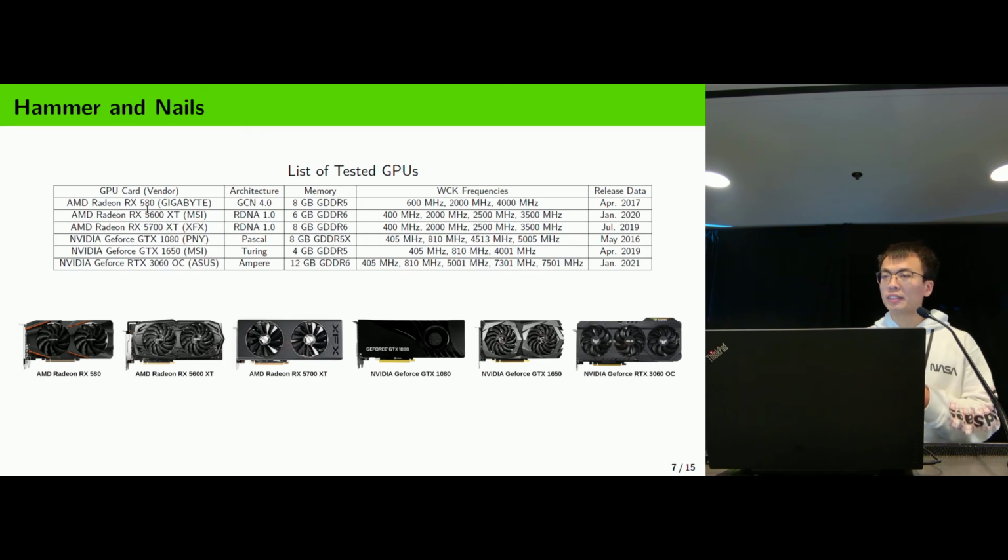This DVFS technique is independently implemented for the discrete GPUs, and for those integrated GPUs, the voltage is regulated by the CPU VRMs, so that's not in the scope of this work, but definitely we can do some further investigations for those GPUs. Okay.